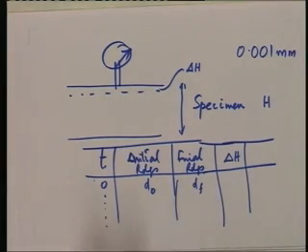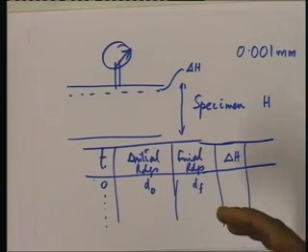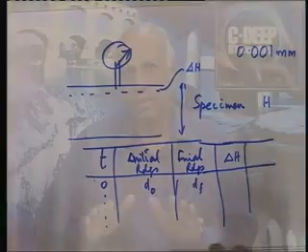This is sufficient to capture the change in thickness that takes place with time, and when the thickness change and correspondingly the dial gauge reading reaches a level which is below the least count of the dial gauge, then the thickness will appear to be steady or unchanging, and that is the time to apply the next increment of load. So, we apply one increment of load, wait for the dial gauge readings to stabilize. This might take anything from 24 to 48 to 72 hours depending upon the type of clay that is being tested.